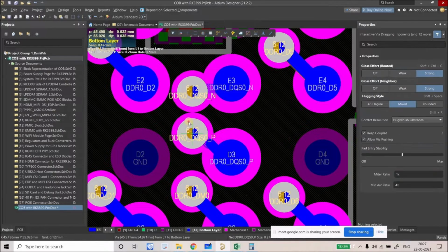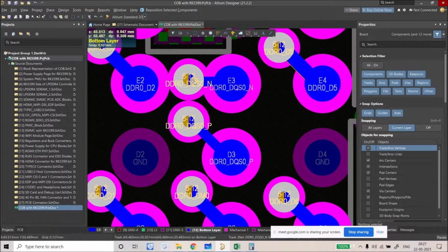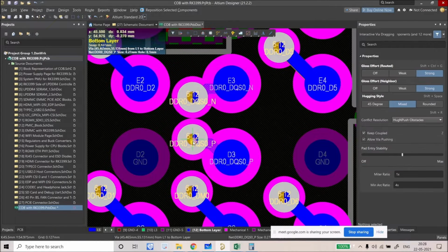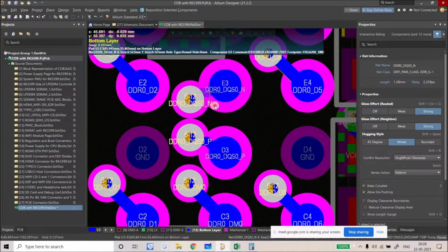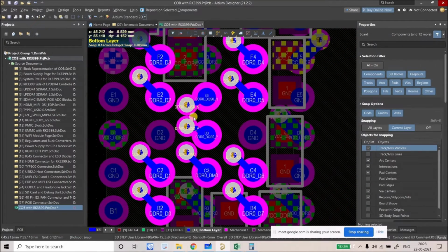So you can say there will be much clearance, right? But the problem will be when we start the layout at layer 1. You're getting it? Right now you can see this area is utilized by these two vias, but we have this area free for tracks, right? But when we place this here and here, this will also be occupied by the via, right?